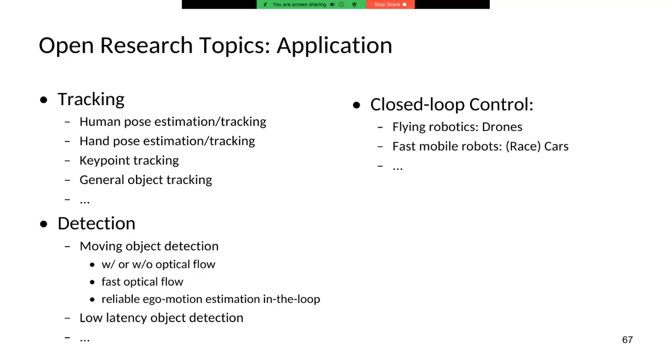And then finally, what is also very open is closed loop control. So closed loop, like vision in the loop, essentially, where you have an agent that takes as input your measurements, such as events from a hybrid camera, some other measurements like IMU data, and you basically give commands to the robot to behave in the way that you define, goal-oriented behavior.